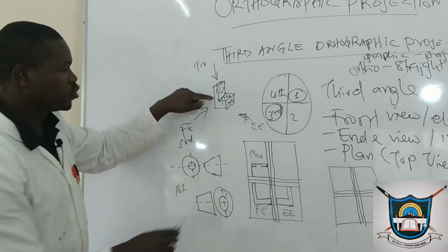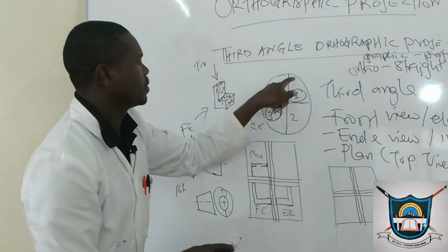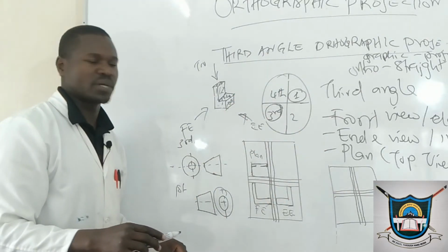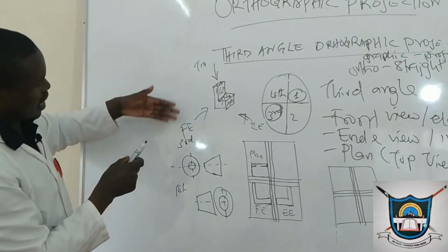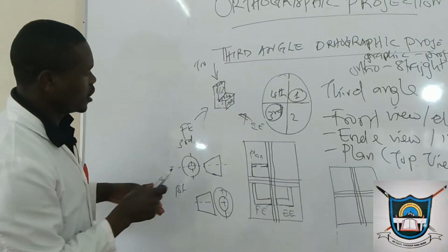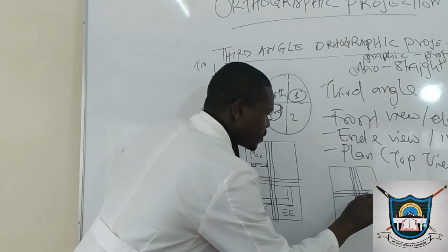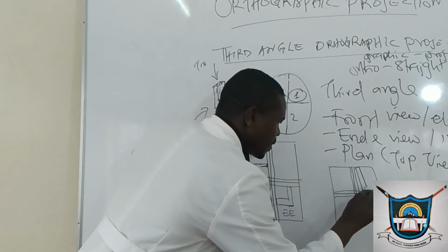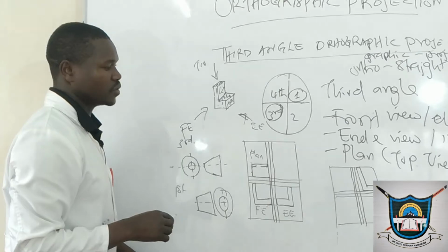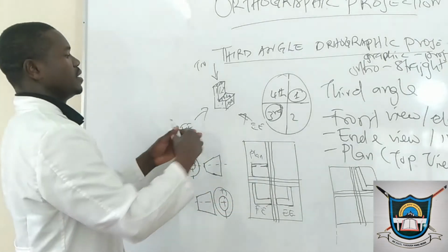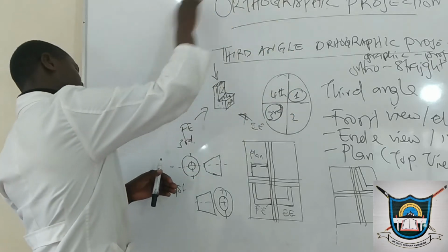So this should be drawn at the first angle. My front elevation comes at the first angle, as per the first explanation. We maintain this as our front elevation. We see such a figure that will look like that, an L shape. That's our front. From that, I see this is the end. We said you look at this side, you draw it behind.